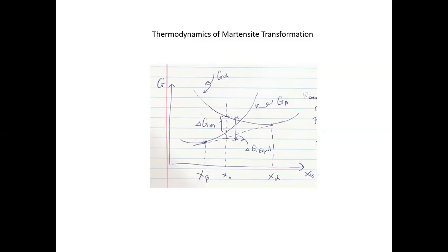lower curve, right? But in the case of equilibrium, what you should really have is that in this particular case, you have coexistence, so you construct a double tangent, which are tangent to both of these free energy curves. If I choose this to be my, let me do the notation. If this is my starting composition, right?